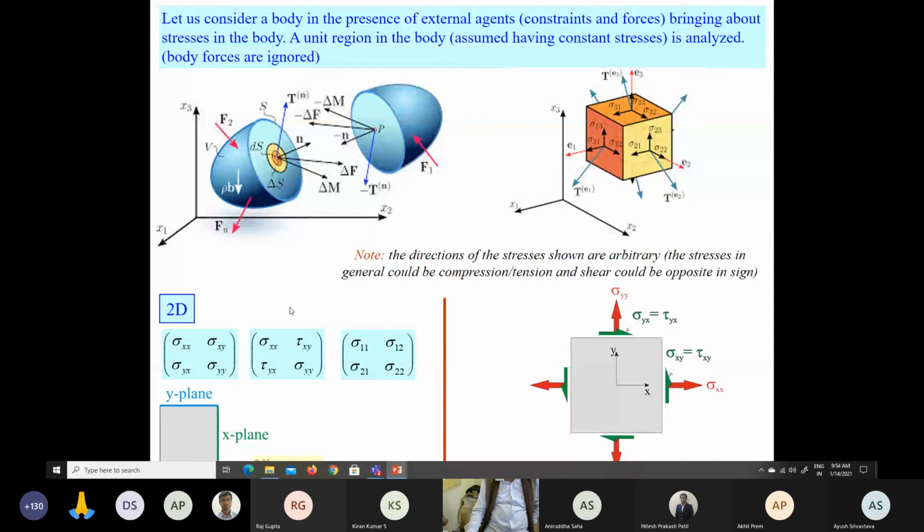So in 2D we can write it in this fashion. It's taking the form of an array format, as you can understand. So we have the diagonal elements here. Later on, you will realize in 3D cases, finally arrange it in a diagonal fashion. The normal stresses are along the diagonal and the shear stresses are filling up the other elements in the array.